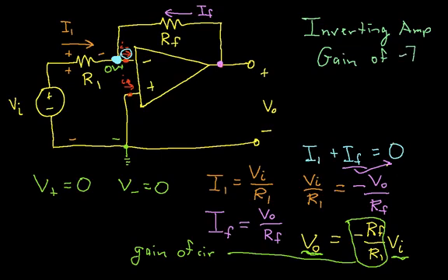Well, then what we would do is we would start with this circuit, that is an op-amp connected with R1 and RF as shown. We could arbitrarily choose a value for R1, so let's choose R1 is equal to 1 k ohm. Then to get a gain of -7, we would need the ratio between RF and R1 to be 7, which says that RF would be 7 k ohms. So that's pretty much all there is to doing this design.